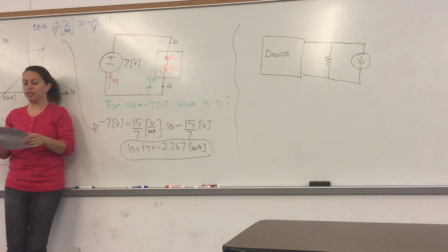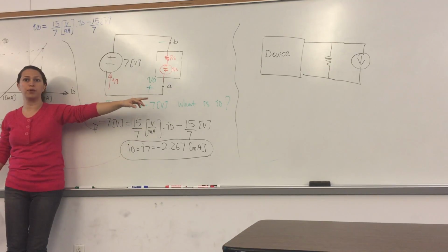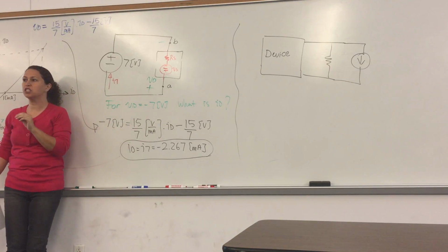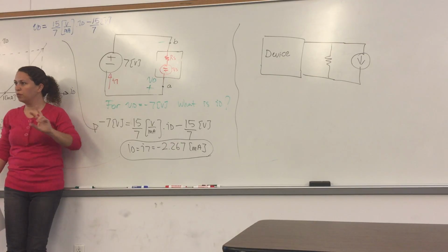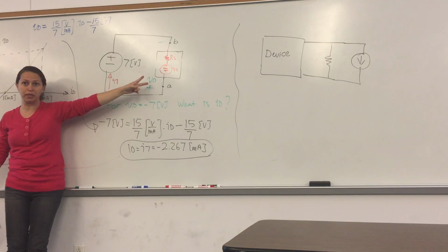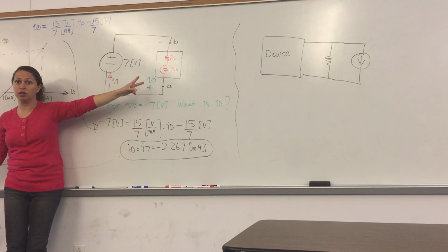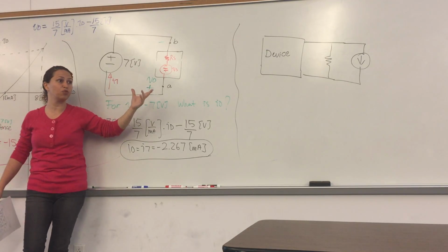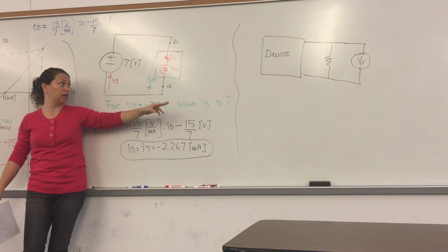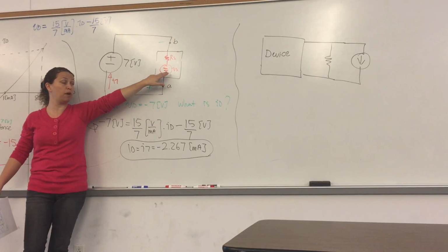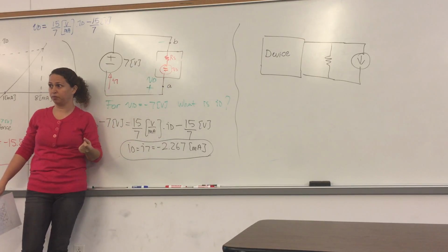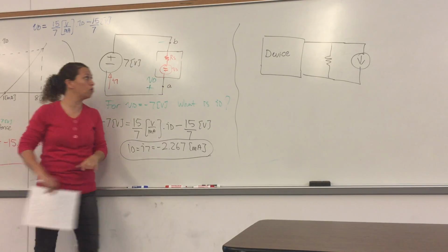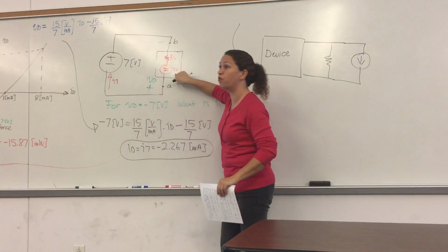Also in those questions, that's what we have also in that new problem that we're going to discuss now. When it asks for the power absorbed or delivered by the device, remember that the device is composed of two components. One big mistake that's generally made is, when the question asks what is the power absorbed by the device, people would calculate the power absorbed by this voltage source, and that's wrong. That's actually missing. Okay? The device is composed of this resistor and the voltage source.